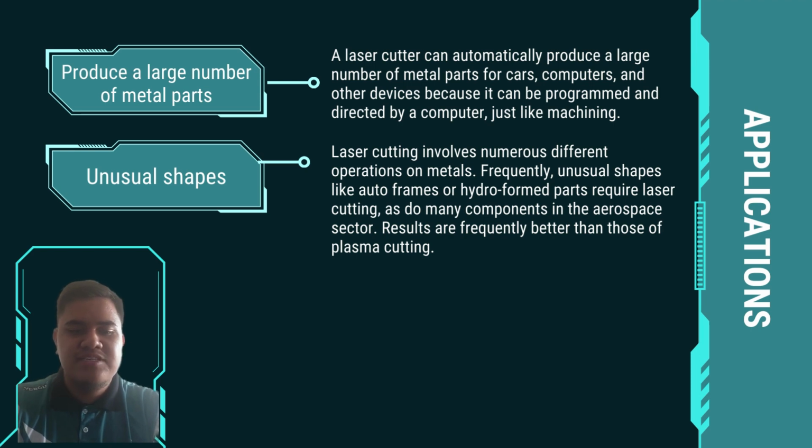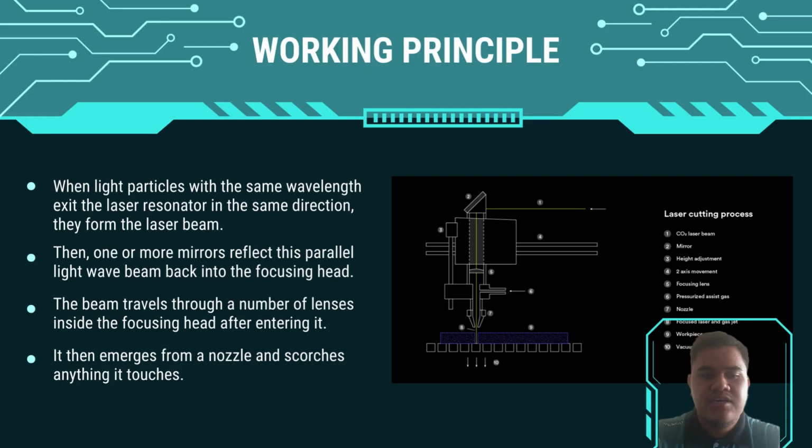A laser beam focused by a lens produces a remarkably strong single point of light. This powerful light instantly melts or vaporizes the material where it strikes. The proper selection of the laser and workpiece parameters determines the laser cutting process and cut quality. Cutting quality deficiency may be related to slow process drifts and disturbance brought on by changes in power and spatial intensity distribution, as well as perturbations to optical integrity. There is a lot of research being done on laser cutting to improve the cut quality. Numerous control variables or parameters, including nozzle misalignment, cutting speed, and focal position, affect the quality of the cut.